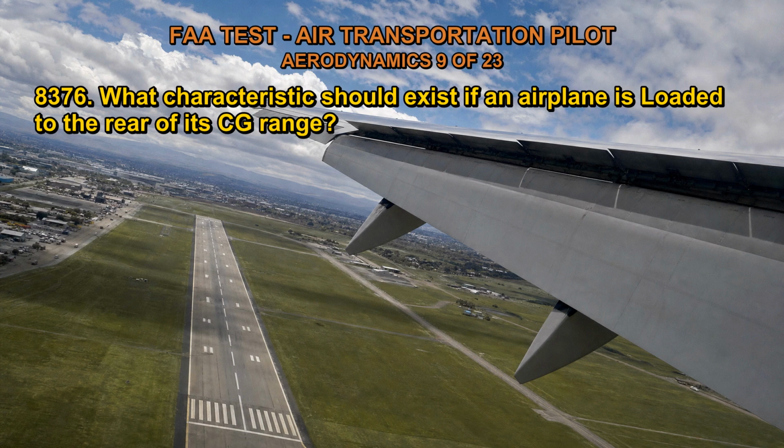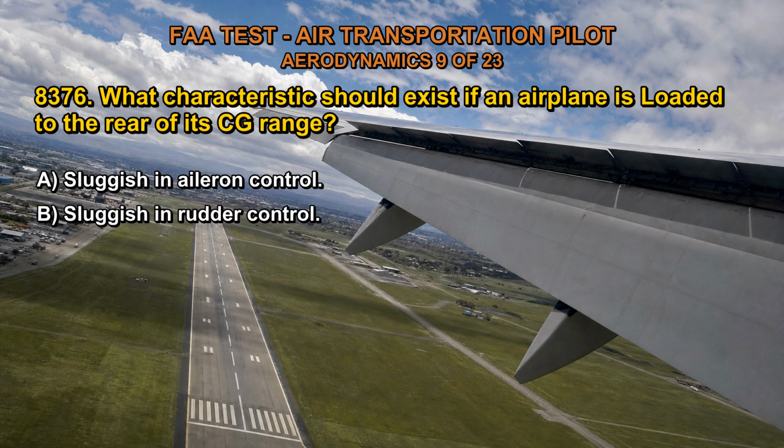8376. What characteristic should exist if an airplane is loaded to the rear of its CG range? A. Sluggish in aileron control. B. Sluggish in rudder control. C. Unstable about the lateral axis.